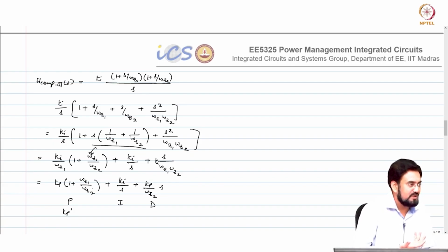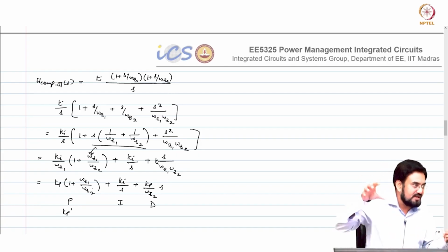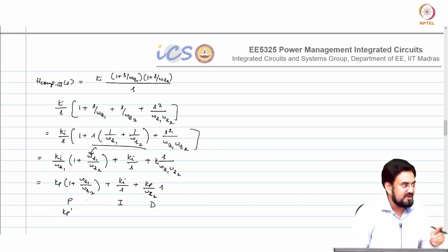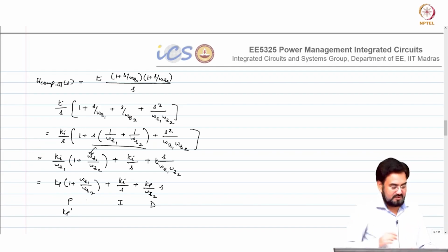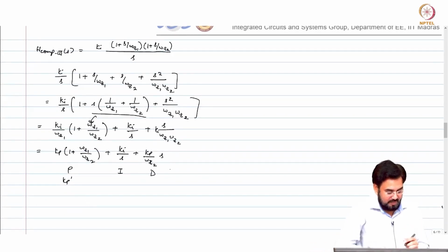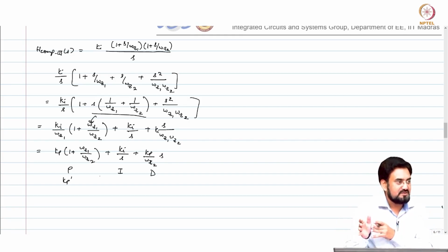Okay, so it will be 1.1, no difference, but we are considering omega z2 as at resonance the other one half, so you will get a 0.5 factor here. So your Kp which you may require in, let us say, Pi 4 or so, here it will become 1.5 times of that. Okay. And this effect we already consider when we calculate the values, because when we calculate the gain, we consider the effect of second zero. Okay, so that will be already taken care in that.